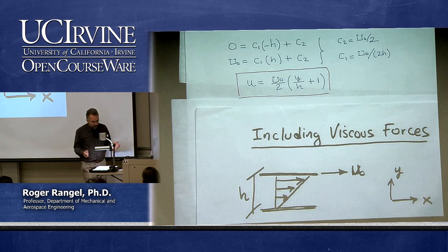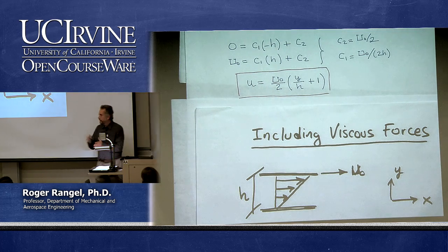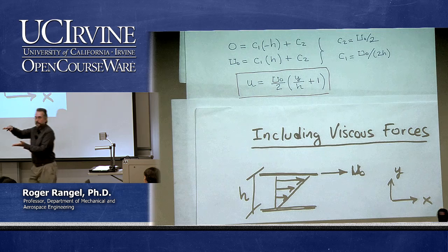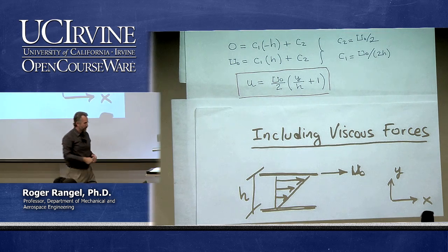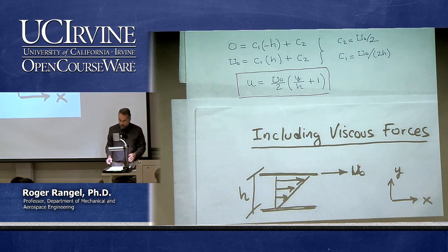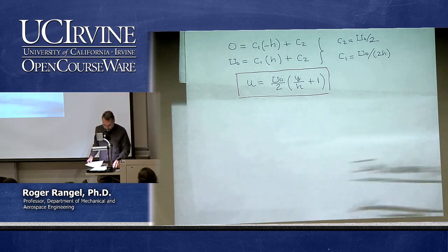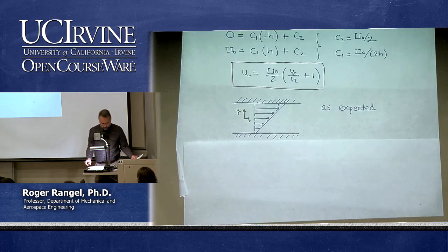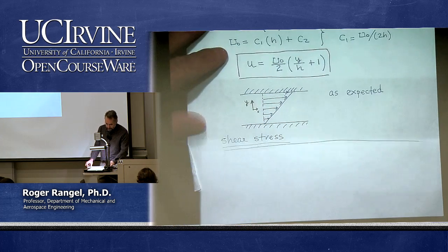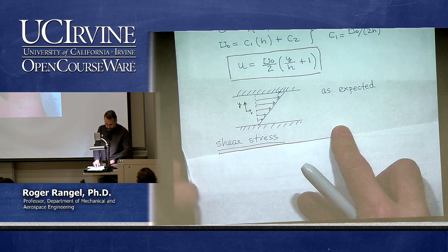And the problem is pretty much done. I verified that a Newtonian fluid in a gap such as the one created when I have two parallel plates with one plate moving has a linear profile and satisfies the equation including the viscous term. So this is expected. Now, what else could I be interested in? It's written right here at the bottom.